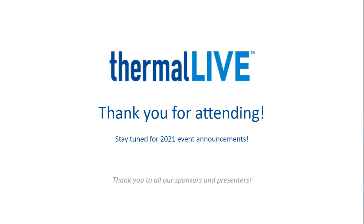can move heat maybe left to right, but not in and out of the material as well. And so they can be challenging materials to work with in terms of heat spreaders. But again, they're highly passive. They're solid materials. They package very nicely. They can be extremely thin and still provide high effective heat transfer rates. So like most of my answers today, it depends on the application. But it's always an interesting material to look at when packaging is a main concern.